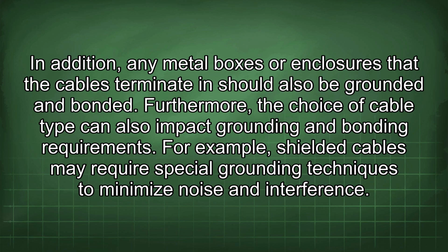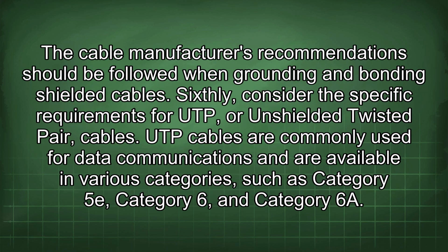Furthermore, the choice of cable type can also impact grounding and bonding requirements. For example, shielded cables may require special grounding techniques to minimize noise and interference. The cable manufacturer's recommendations should be followed when grounding and bonding shielded cables.